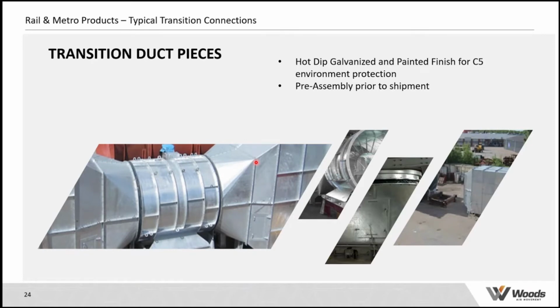They're generally made from mild steel, similar to the fan casing. They can be hot dip galvanized, which provides an extremely durable finish, generally acceptable for the application. These fans are normally mounted inside the building. They're not subject to the atmosphere, so it's a reasonably okay environment, and you easily get your 20, 30-year life from the casings. And those transition sections are normally made in pieces to allow easier transportation, and more importantly for movement and installation on site. To move them in one piece would be quite difficult.